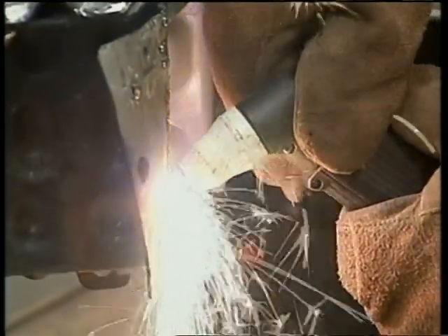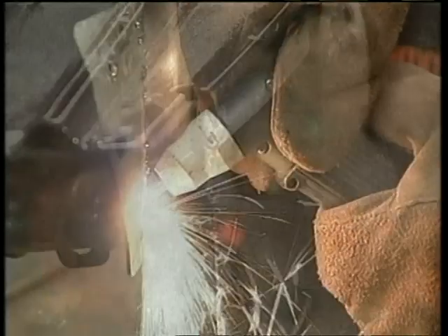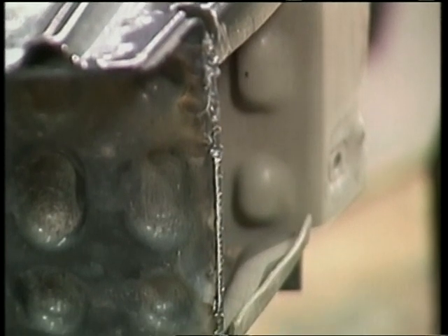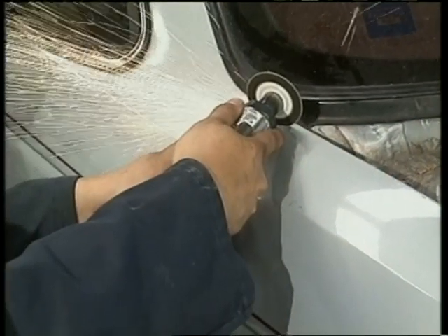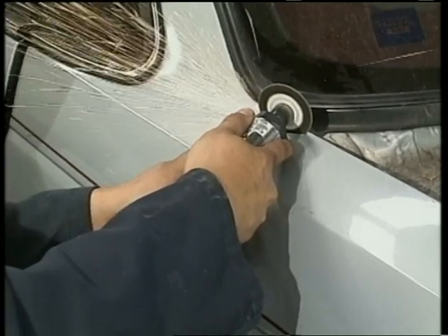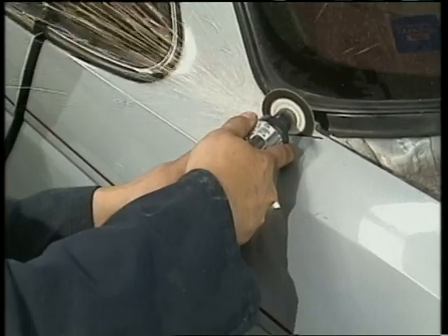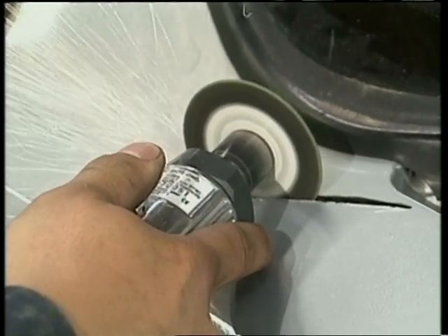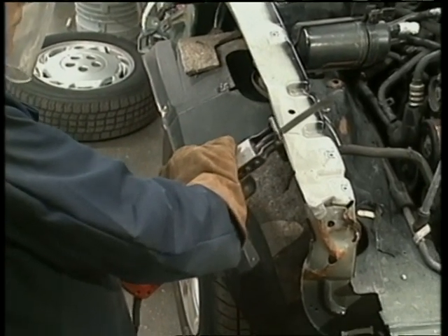The advantage of the plasma cutter is that it'll cut nearly any metal and can make intricate cuts. The downside is that it'll leave a hamster-nibbled edge that needs filing, grinding, and smoothing. An air cutoff tool is a good choice for plastics, fiberglass, composite materials, and sheet metal work. It's the most commonly used tool for almost all cutting applications and is the preferred tool for making nice, clean cuts.